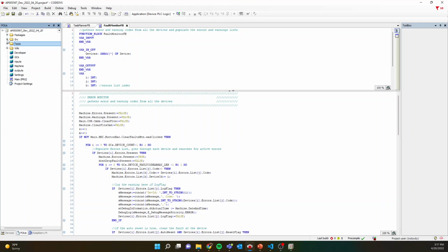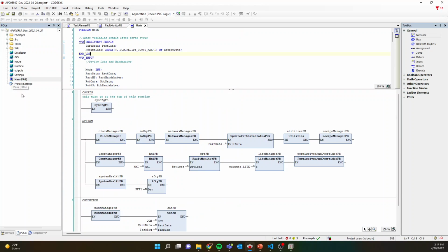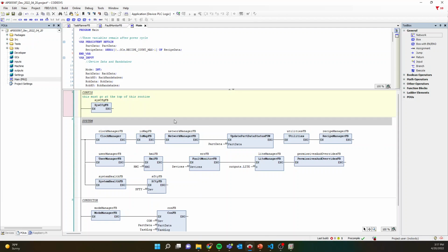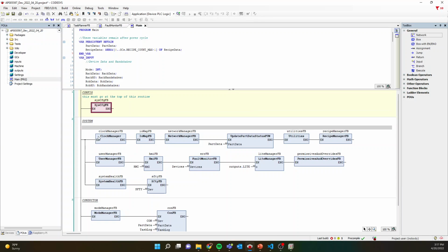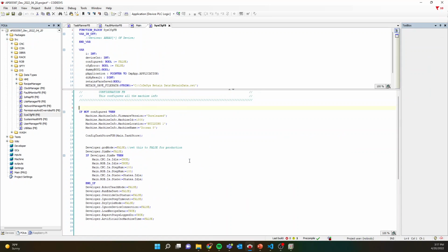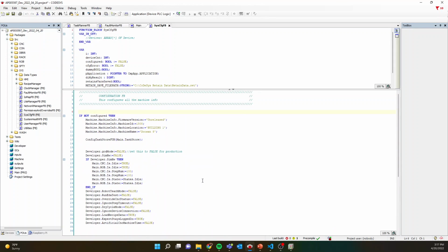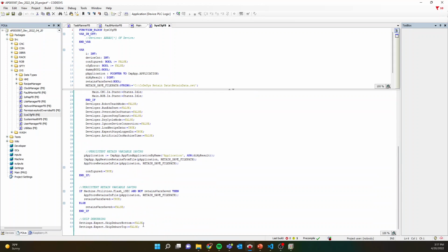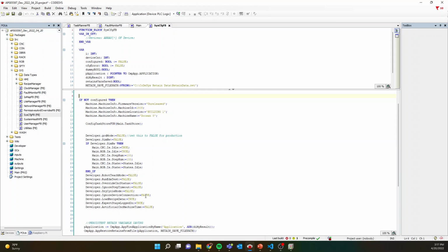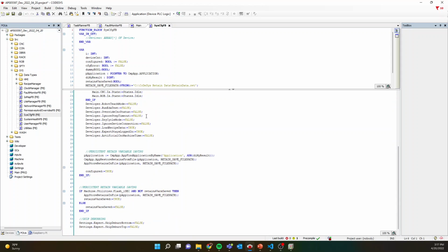Like I said, the entire code is based in this main program. So anything that's housed or run is first called in main, and then main is actually a ladder diagram that runs and executes this code sequentially. So the first thing we call is the system config function block, and we can double click that to open that logic up. Typically this is something that we call once, but make some configuration level settings in here.